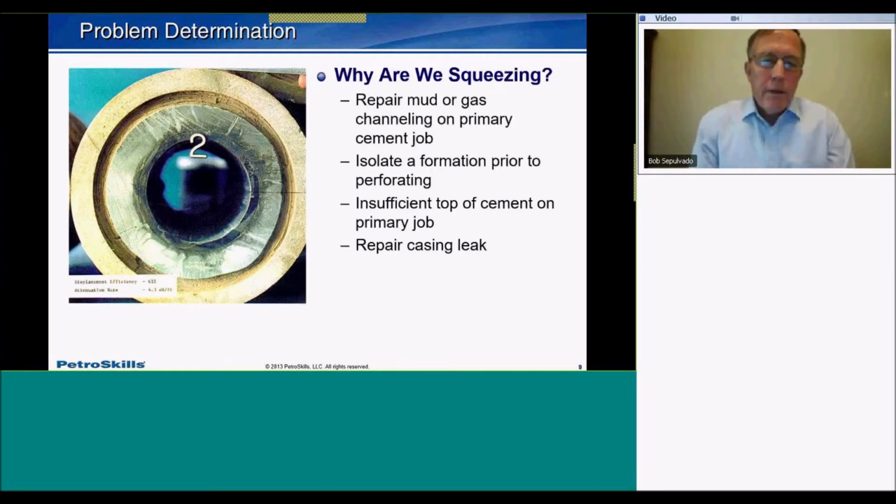All right, we're going to spend a little bit of time on this slide. What you see on the left is a picture of a full-scale test from a 60-foot test well. Service companies, some of them, have the capability of doing full-scale testing, displacement studies. Some operating companies may as well. So what you're seeing here is a post-mortem of a displacement test that was cemented in the well and taken out, and then it can be cut up and evaluated in 1 or 2 foot sections.